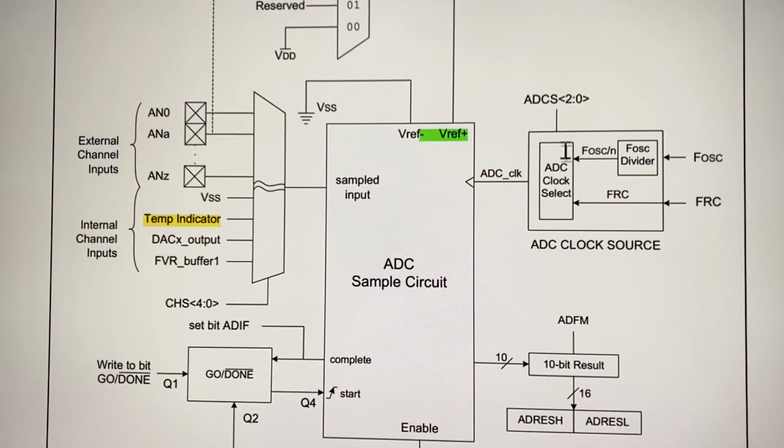The ADC converter requires a clock selection. The clock can come from the crystal or from another clock source, and you can select it. So the clock allows you to select the conversion speed, or the conversion time that it'll require to have a conversion ready. Every time you sample an input voltage, the voltage has to be converted into a 10-bit result, and it'll take a conversion time.